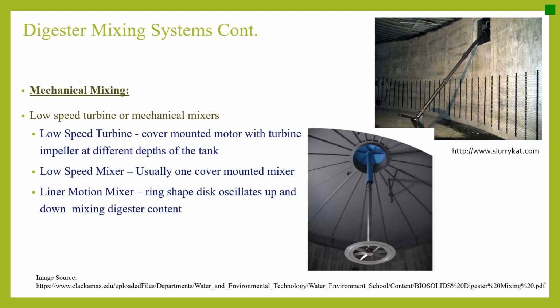And there is mechanical mixing that is done by low-speed turbines or mechanical mixers. Low-speed turbines are usually cover-mounted motors with turbine impellers at different depths of the tank. Low-speed mixers are usually one cover-mounted mixer, one big one that covers the whole tank.